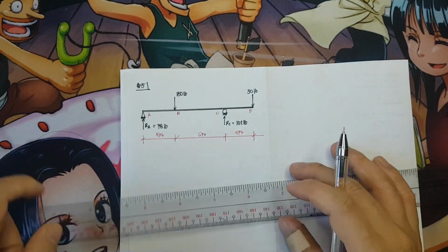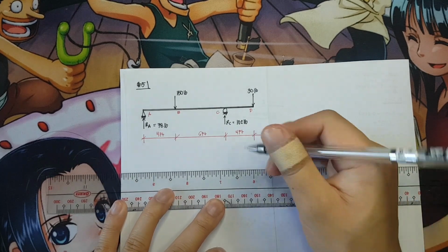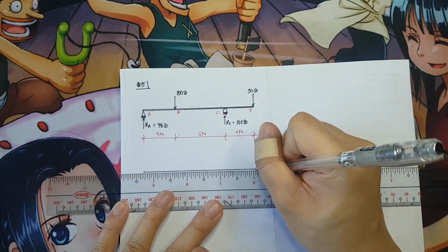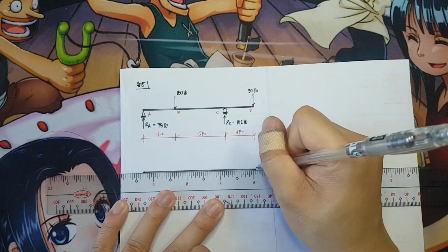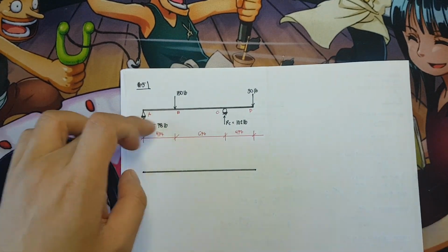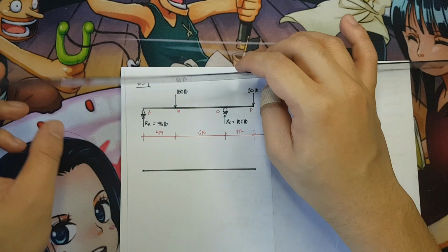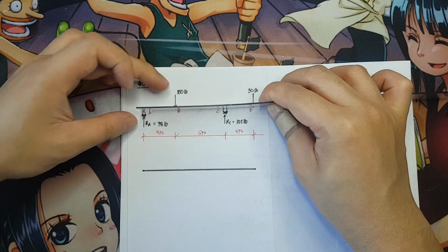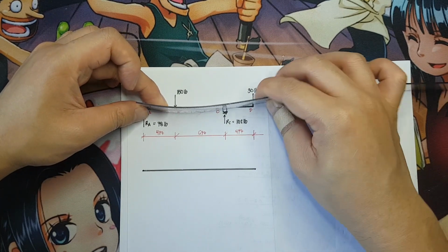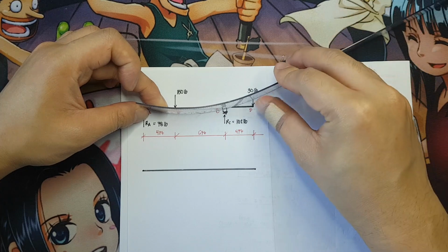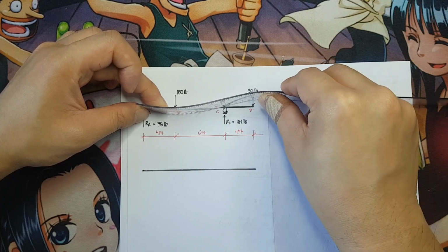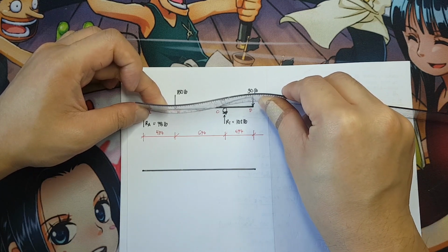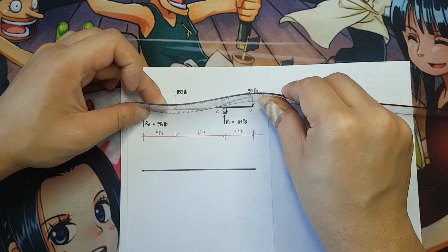It is better if we imagine how my curve would look. In doing so, we will ask the aid of this very elastic ruler. Take note, you have a support at A and a support at B. So imagine this ruler is your beam and you have a load at 150, so it would deflect this way. And you also have a load of 30 at D, so it would deflect this way. So the deformation of the ruler would most likely be the image of your elastic curve.